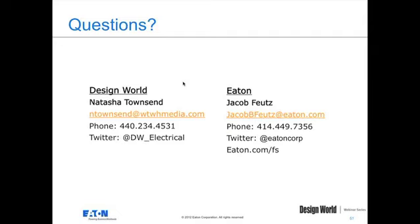Okay. And second question posed, how are functional safety standards evolving? Yeah, so one of the primary things is the different standards that are coming up. As I mentioned in the presentation, EN 954 was a functional safety standard for a very long time, became very popular, but only addressed control architecture. They were concerned that that standard did not take into consideration the reliability of the components, the diagnostic coverage achieved, or the common cause failure. So they built the 13849 standard around that. At the same time, a similar standard was being built, the IEC 62061 standard, that did things just a little bit differently. There's already a technical report drafted as far as how they're going to combine those standards. But I think one of the important things to recognize is that eventually in the functional safety world, we'll be looking to a new standard that'll define a collaboration and a combination between the 13849 and the 62061 standard that are there today.